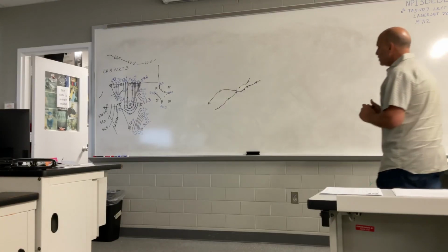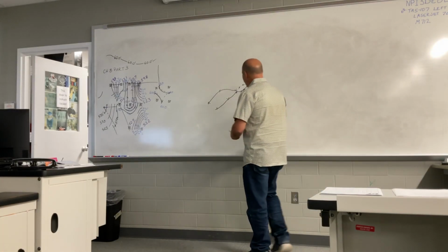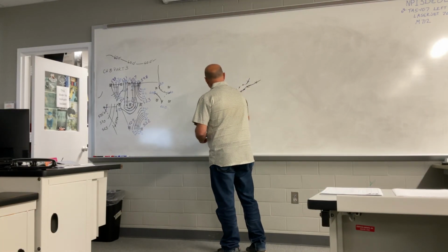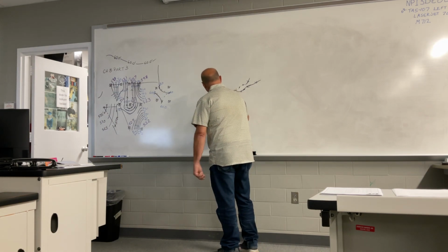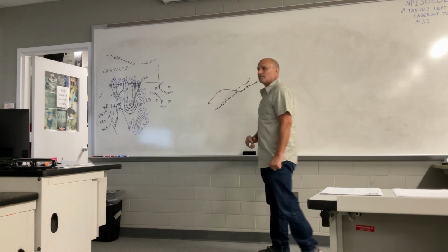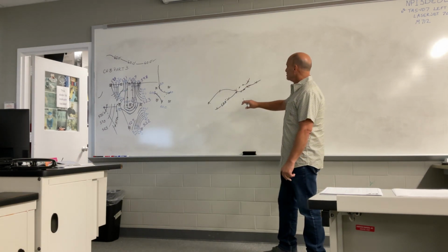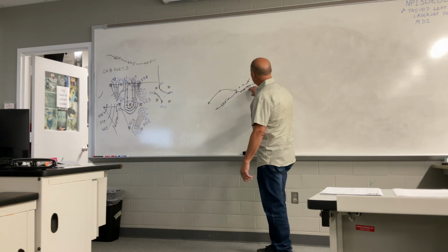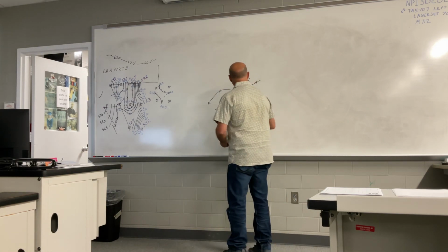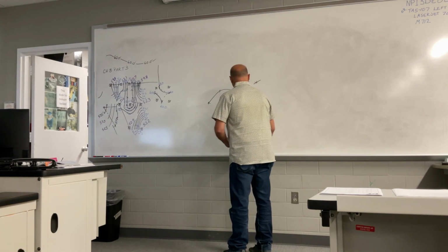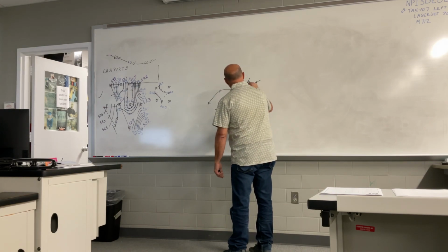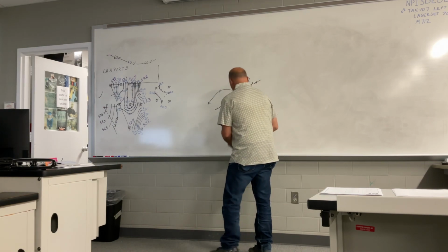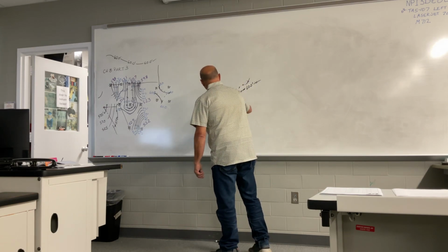Like I said, once you go through, if you use text masking, it will allow you to put that elevation on there. And then if you say, well, that elevation is too close, it's too cluttered right here, I want to move that elevation over to here, you just grab that text, move it to the new location, so it's no longer right here.